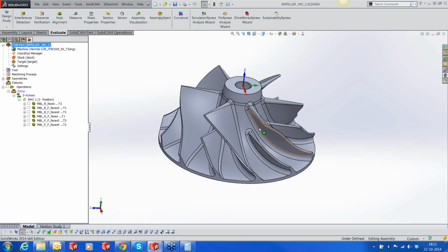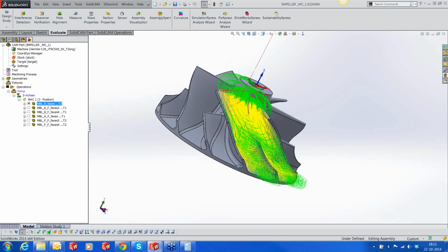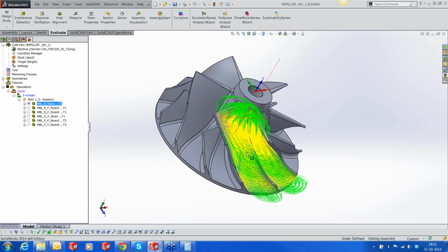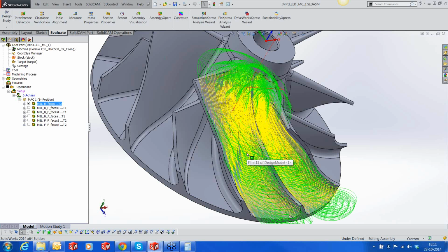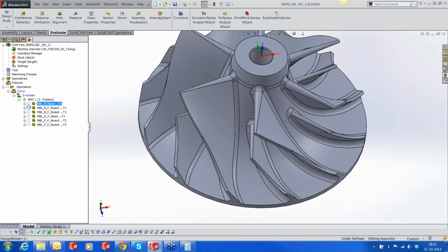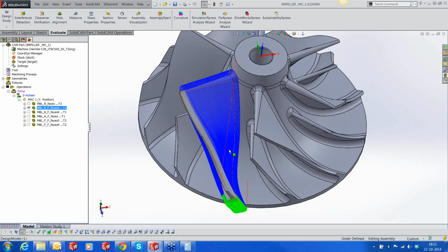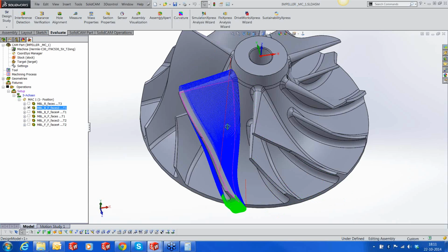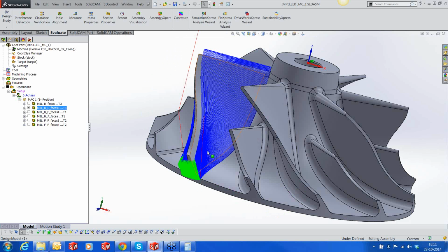We've used roughing, again going from center to out, and this is the tool path that it generates. Very nice. The yellow are the cutting motions, the green are the links. So we're going from center away, very nicely done. And then we have got the finishing of the blade. Now you can see that this was not done completely because this was an area that was left out.